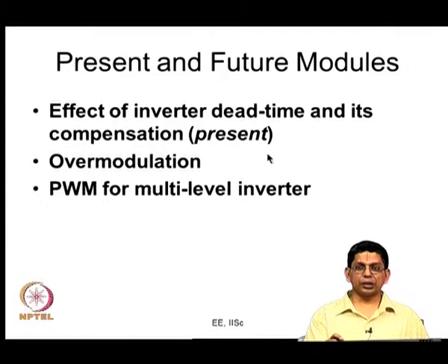So, one of the things that you really do is introduce the so-called dead time, which we just saw in the previous lecture. What do you do? You introduce some intentional delay between the switching on of the complementary devices. There are complementary devices, one is turning off, the other is turning on. Do not do the two concurrently. First you turn off and then you turn on the incoming device. That is the idea, and that is what is called dead time.